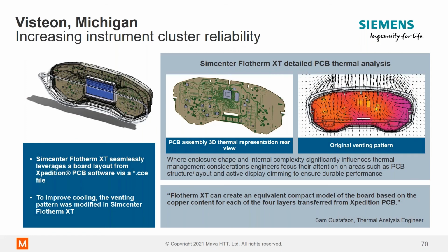If you go to the next slide, we can see that Visteon use and import their very detailed PCBs with detailed components using the Flow EDA bridge. They're able to then simulate what the temperatures and what sort of airflow is generated around the instrument cluster. And again, the goal here is to make this as reliable and as cool as possible to reduce field failures. Because, with an instrument cluster, you can't just swap out the PCB. Chances are you have to swap out the entire cluster, and that can be on the order of thousands of dollars to replace if something fails, especially during the warranty phase.